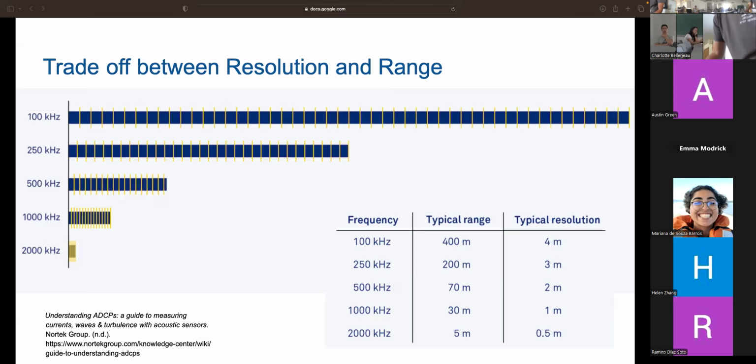We also do a little bit of processing ourselves where basically these first bin or two, we just ignore. It's called blanking. One, because when you emit sound, everything around it would also kind of insonify and echo around it, especially on a ship. And so you can get a lot of contamination in those first few bins, so we just ignore them usually. But that also, at least for the ship component stuff, helps ignore turbulence coming from the hull itself. So there are ways around it, and you just kind of have to be careful.